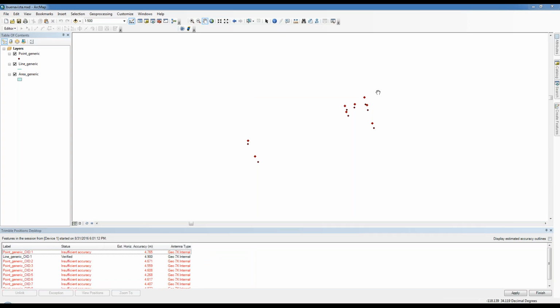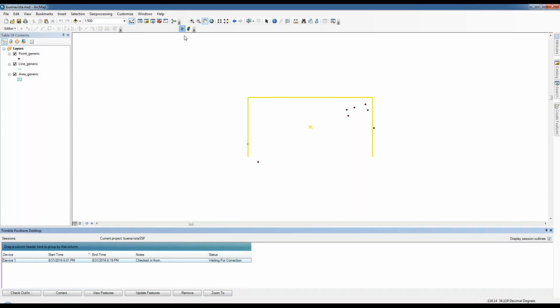Let's see. Does this update features work with an enterprise geodatabase? Yes, it does. It supports file, personal, and enterprise geodatabases. And so however you have ArcMap connected to your geodatabase, if it has authentication information, if there are secure feature classes, et cetera, whether database authentication or Windows authentication, we inherit however you're connected to those feature classes through ArcMap. And so if it's a particular version, one of the workflows that would be common in an enterprise would be I'm working with version data. So that's all supported.